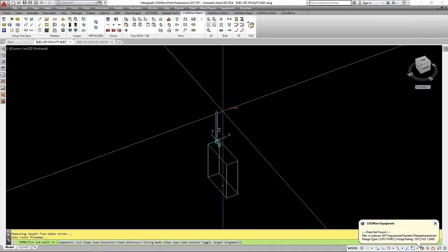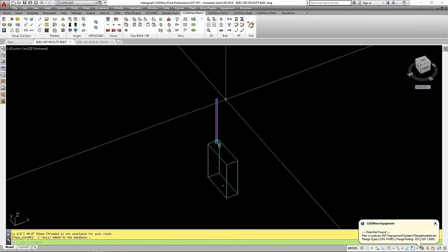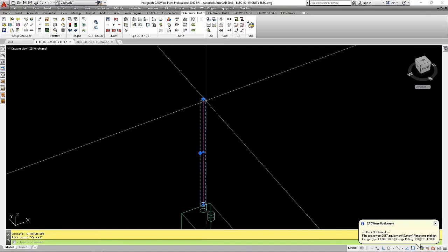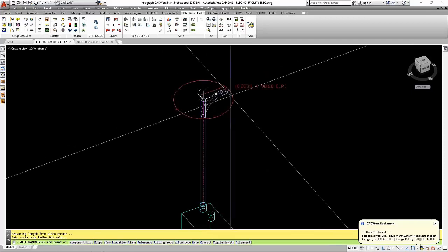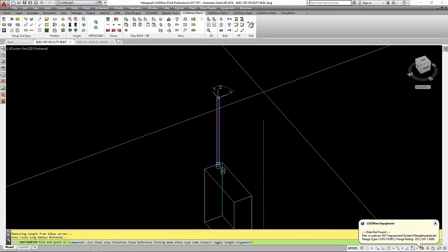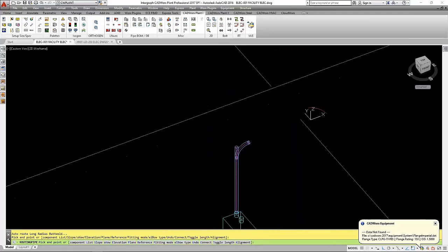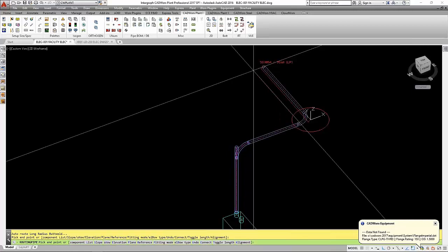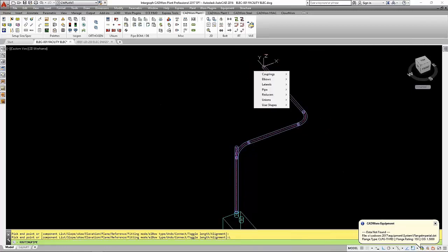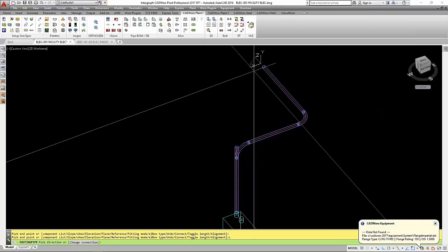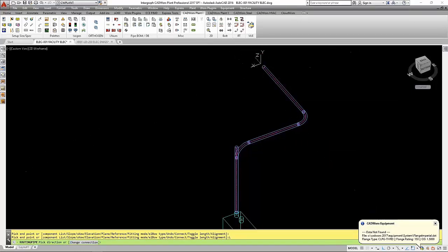And it's just CADWorx at this point with a piece of pipe that's been specified as conduit, so straight off the nozzle. I want to make adjustments, just hitting the plus sign, and there I'm going to be able to elbow off of that piece of pipe, and then with CADWorx I can put in the bend of any radius. So we just simply have a bend in there that's called a bend, and then I can go to user shapes and go after all sorts of 3D blocks, and here we have a block of a T.